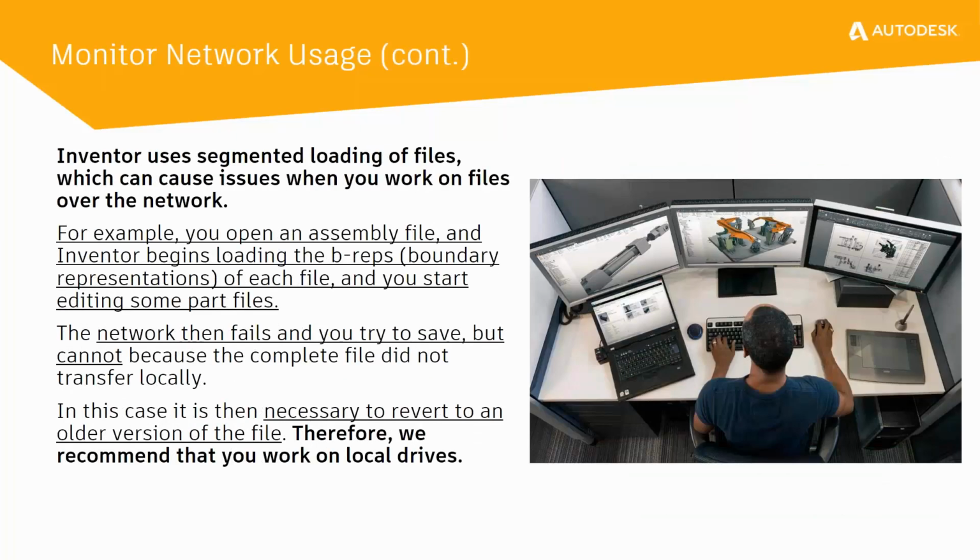And finally, monitor network usage. Inventor uses segment loading of files, which can cause issues when you work on files over the network. Another good reason for you to work locally, and the best way of doing that is using Vault.